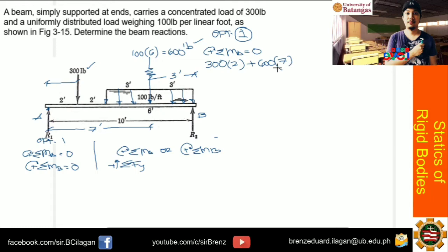So, 600 times 7. And then R2: what moment does it produce? It is counterclockwise, therefore it becomes minus R2 multiplied by 10. Okay? So, I will just transpose it to the other side of the equation, so it becomes positive, and the equation equals R2 times 10. Therefore, R2 will have a value of, let's just use the calculator.